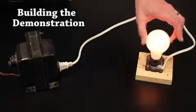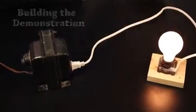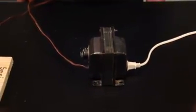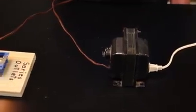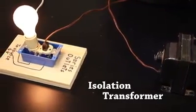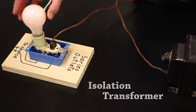If you want to do this demonstration yourself, you must have an efficient transformer, and you should try to have the same wattage bulbs at their appropriate voltages in the primary and secondary circuit. For this purpose, we used an isolation transformer, that is, a transformer with a turn ratio of 1 to 1.